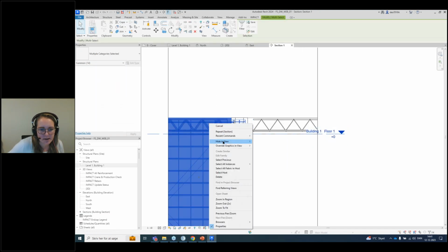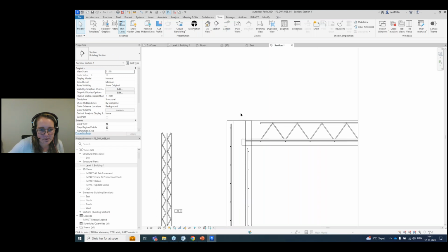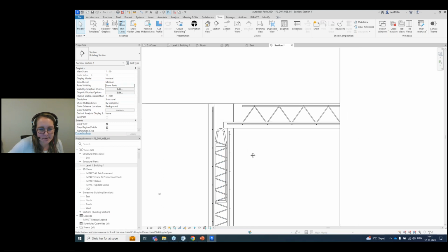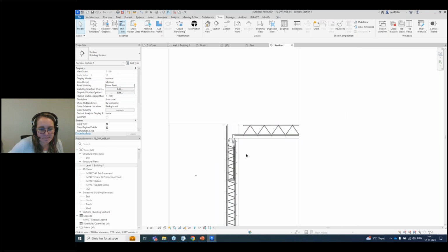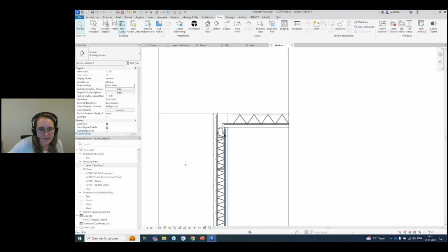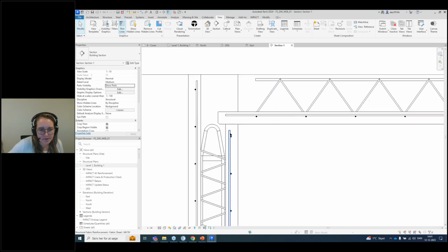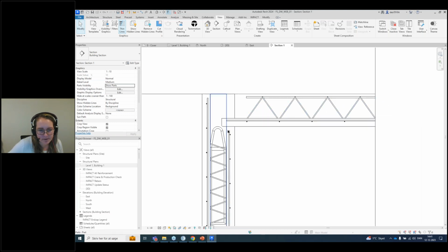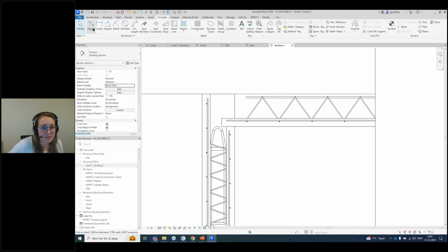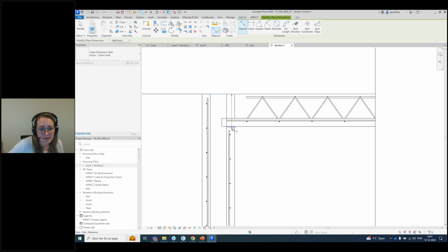If I hide all those in the view, then here you need to set it to parts, right? Because then you can see the parts of the wall. Here you can see my double wall. I have made reduction for slab and that's 200, right? The one that we just set.